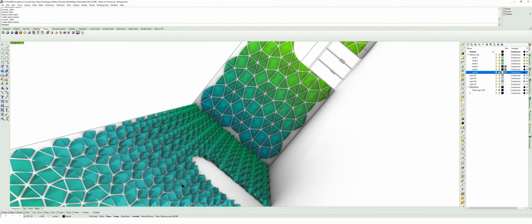That will go ahead and switch it, but you can see in some cases, like right here, this is actually flipping out instead of in. So we want that to be flipping consistently rather than some cases where it's going out, in some cases it's going in. We want it to always be going the same direction. How do we stabilize that? Well, we need to relate our curve back to our original surface. So I want to evaluate surface by typing evaluate surface. And if you're looking for it, it's in the surface tab under analysis.